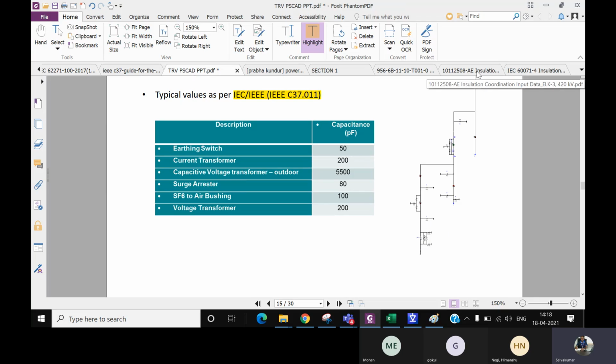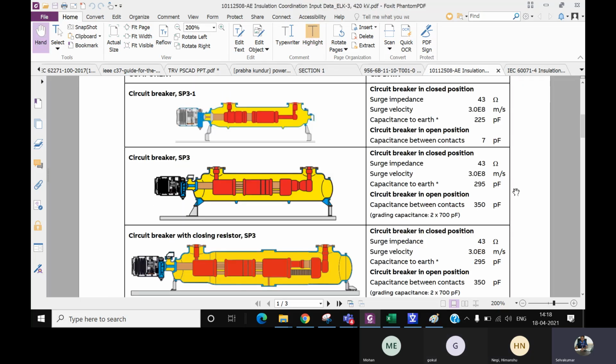Once we asked for the capacitance value on the HV side of the auto transformer. The manufacturer himself gave 1400 picofarad at the beginning. Then we ran a simulation for 2 months and everything was exceeding. We went back to them and now they have given 10,000 picofarad. Originally he had given 1400.